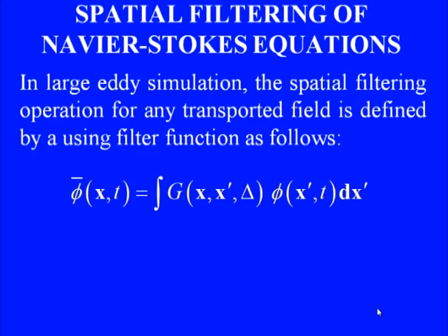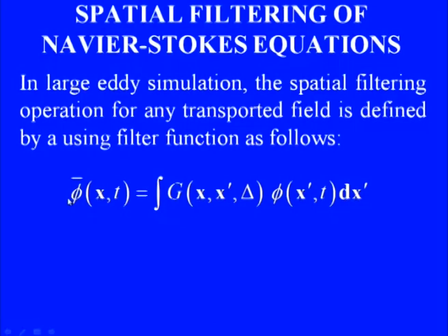For the time being, let us have a look at spatial filtering. The spectral filtering works in an analogous fashion. Okay. So, in large eddy simulation, the spatial filtering for any transported field, which could be one of the velocity components, it could be temperature and so on, is defined using a filter function. So, suppose phi were our flow variable.